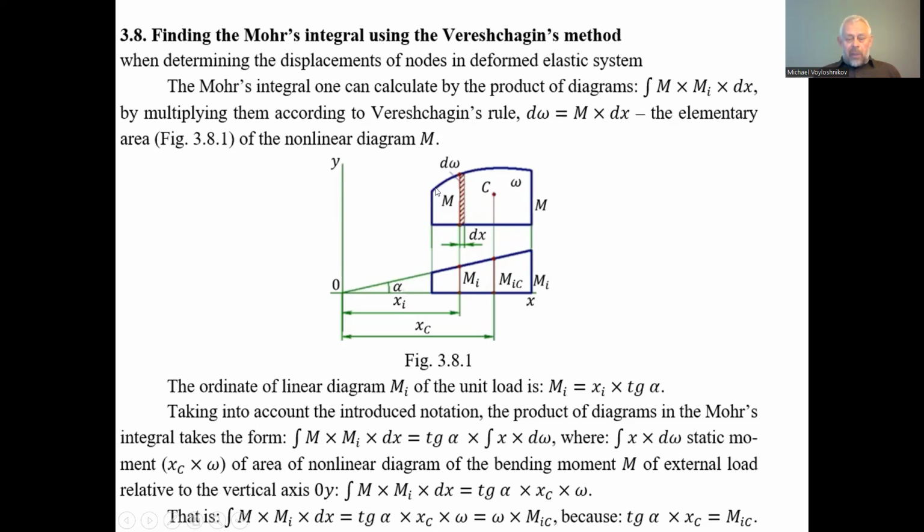It can be a trapezoid. We have the formula as a half total of the ordinates at the ends of the trapezoid diagram multiplied by the height of the trapezoid. For the curve, it will be difficult. Sometimes we have to find the area using the formulas for the parabolic, or maybe for the cubic parabolic shape of one of the sides of the curvilinear trapezoid.